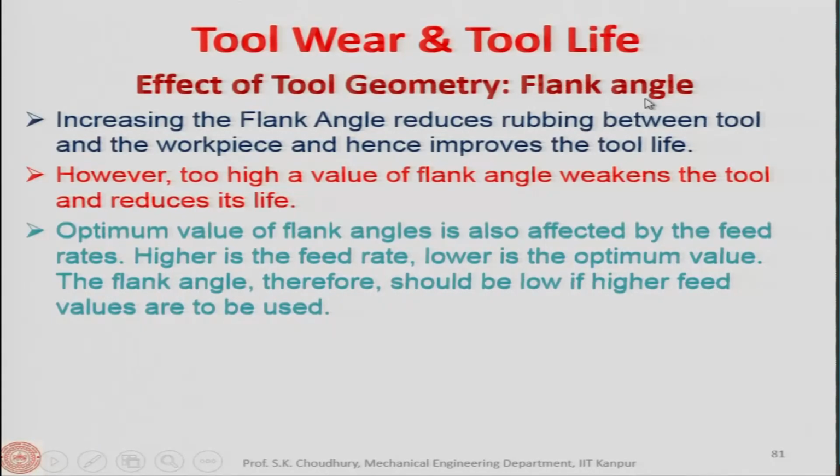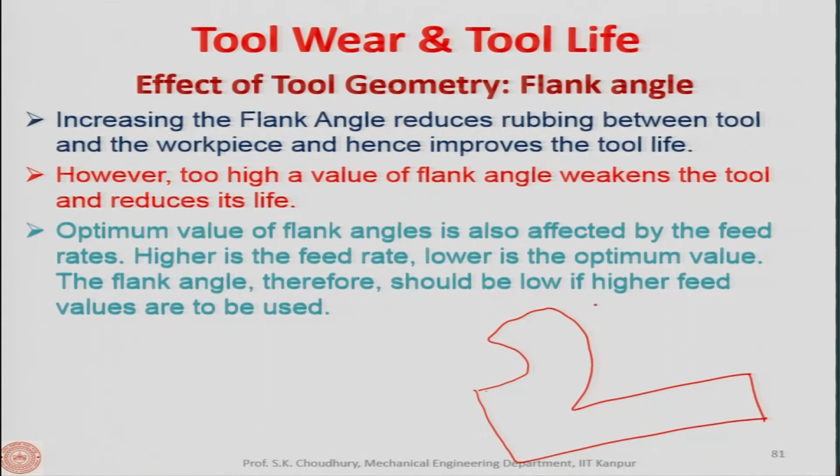Now, let us see the flank angle. Now, increasing the flank angle reduces the rubbing between the tool and the workpiece, and hence it improves the tool life. Once again I will remind that if this is the tool and here is the workpiece, this is the workpiece, this is the tool, all right. So, this is the flank face or the flank surface, flank, or as I said that it is the clearance face also it is called, and this is the flank angle.